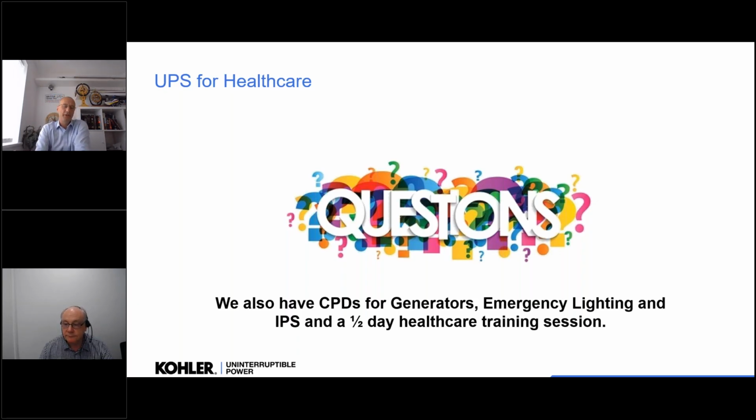Yes, it does depend on the size of the application. It can be cheaper. The benefit of an ATS with dual supplies is that it will choose the supplies available. This is where we get a lot of confusion: people think that if you've got a dual supply into the UPS and you lose the main supply feeding the rectifier, the UPS will swap over and use the secondary source to feed it, but it doesn't.